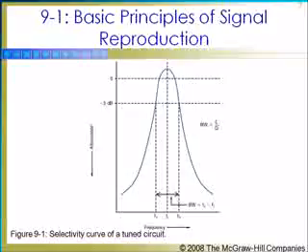As you can see on the graph, the rate of attenuation or roll-off of an LC-tuned circuit is gradual. Adjacent signals will be attenuated, but in some cases, not enough to completely eliminate interference. Increasing the Q will further narrow the bandwidth and improve the steepness of attenuation, but narrowing the bandwidth in this way can be taken only so far.